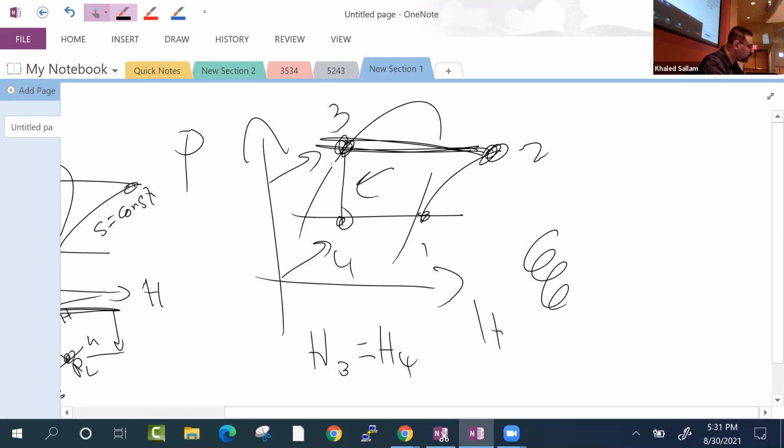What's wrong with having this go to a turbine? It's wet, excellent. It's wet, and if you're going to have something here, it's not going to be called a turbine, it's going to be called an expander. That technology is not there yet. To have an expander that takes liquid and expands it, meaning lowers the temperature and pressure, and gets work, you need a special design. It's not going to be a regular turbine with plates. You cannot shoot those plates with a water bubble mixture, right?